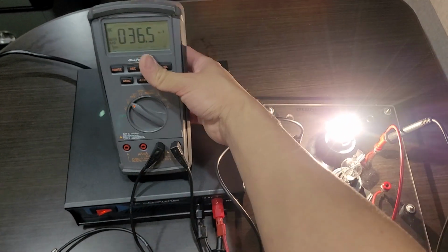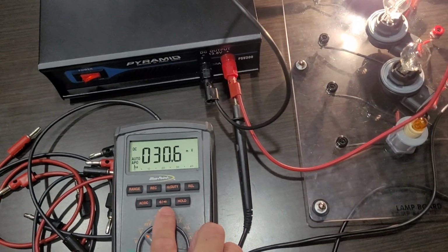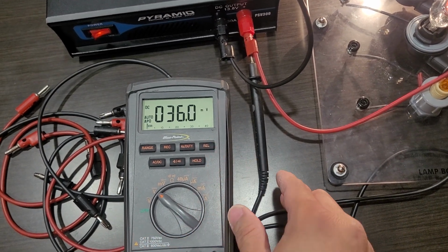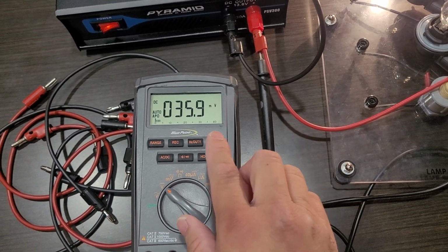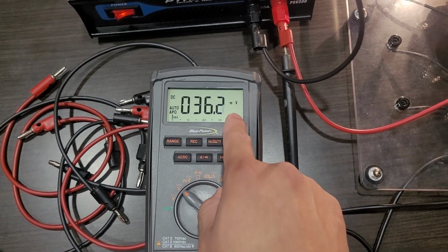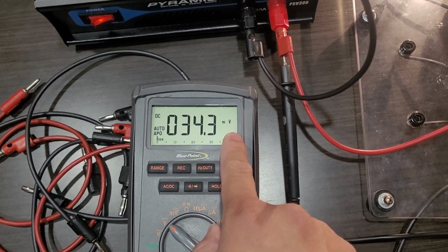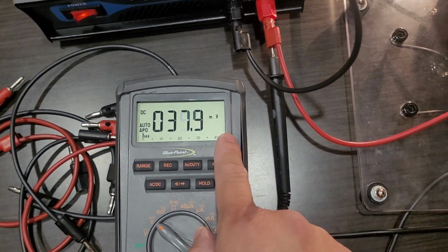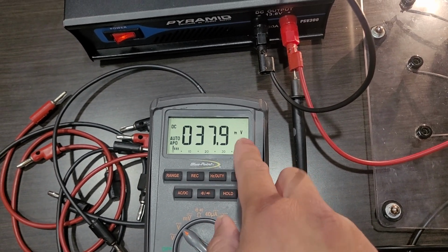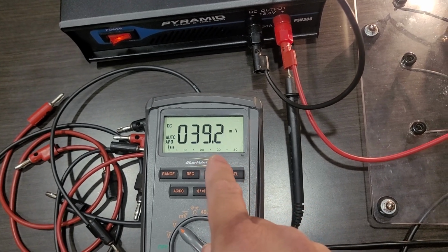Now when I go to my DMM over here, what it's reading is 30 point, sorry, it keeps fluctuating there, probably because I have some movement on the table here. But what it's reading is 35.9 millivolts, which is very important because lots of times what I see students do is when they write the value, they write it as 39 point whatever volts. Okay. Right now, this value is very minute, very small.